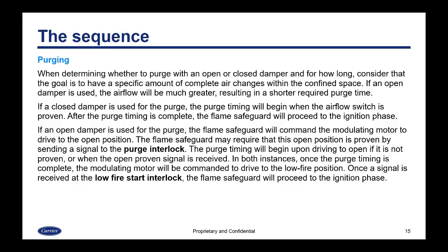In both cases, once the purge timing is complete, the modulating motor will be commanded to drive to the low fire position. Once the signal is received at the low fire start interlock, the flame safeguard will proceed to the ignition phase. And those of you that have been in the boiler room know the cadence, the sound. You can hear the damper closing, and at the end of that you hear the pilot solenoid click.